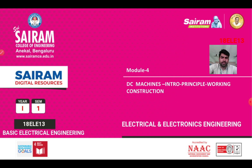In 10th standard and PU classes, we studied the dynamo, right? Similarly, we have a generator over here. And the second one, Fleming's right hand rule, is for the generator. Those three fingers, the thumb, middle finger and forefinger, are mutually perpendicular to each other. The thumb shows the motion of the conductor, the forefinger shows the magnetic field, and the middle finger shows the induced voltage or induced EMF. That is Fleming's right hand rule.